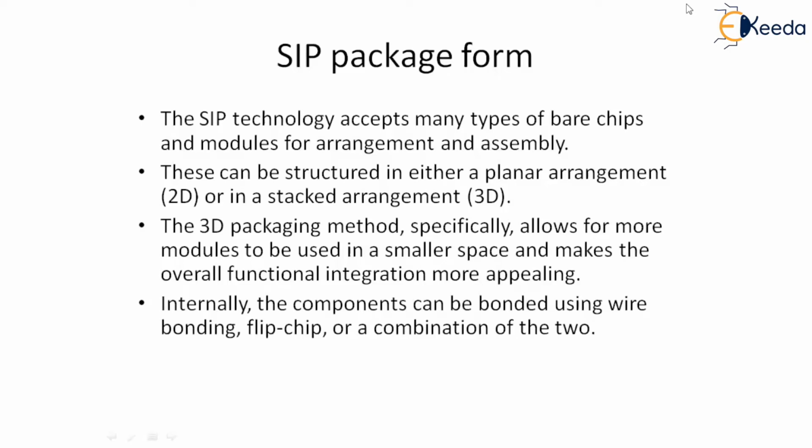SIP package form. The SIP technology accepts many types of bare chips and modules for arrangement and assembly. These bare chips and modules can be structured in either a planar arrangement, that is a 2D arrangement, or a stacked arrangement, one above the other, known as 3D arrangement. This 3D packaging method specifically allows more modules to be used in a smaller space and makes the overall functional integration more appealing.